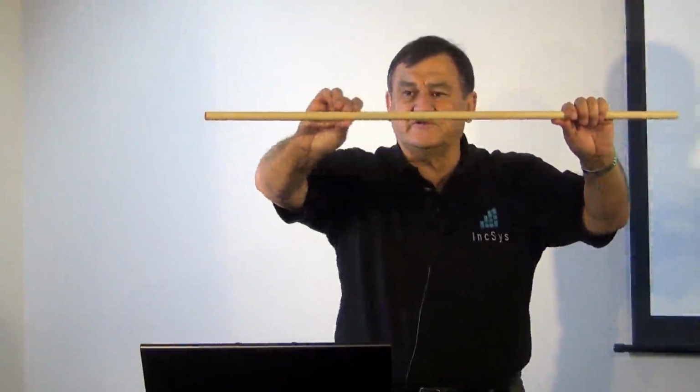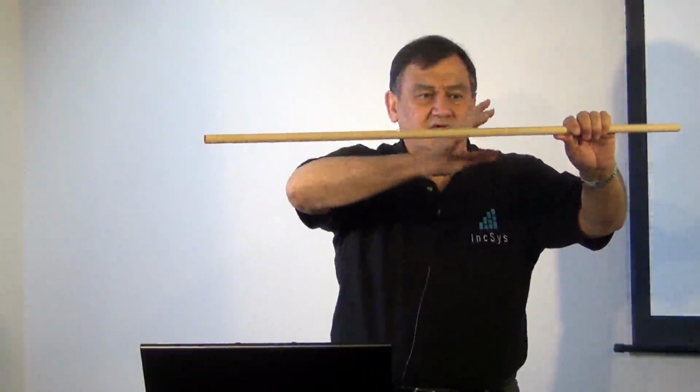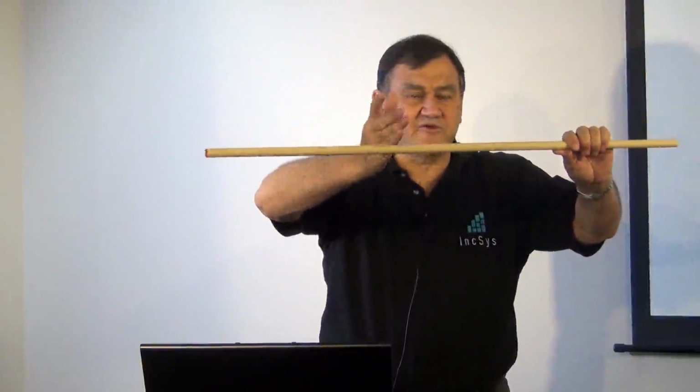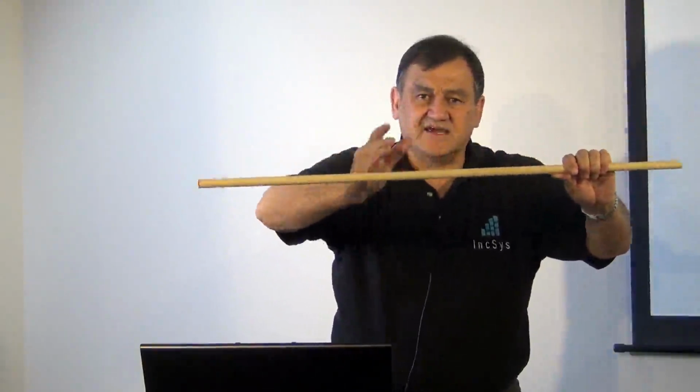We covered that there's no energy used by reactive power exchanges, but it does load up the conductors with current. As that current flows through a resistance, I get a certain amount of what we call I squared R losses, and that's analogous to the friction I talked about with the pendulum.